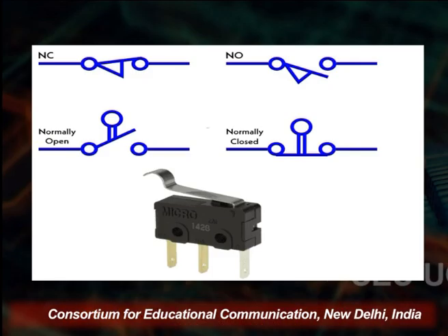The next type of switches is the limit switches. Limit switches are operated automatically by mechanical parts of the machine, or manually by an object in control systems, like the bumper arm in the switch used as an actuator. When pressed or in contact with the object, it changes the direction of flow of the current, hence it changes the position and the operation of the circuit.